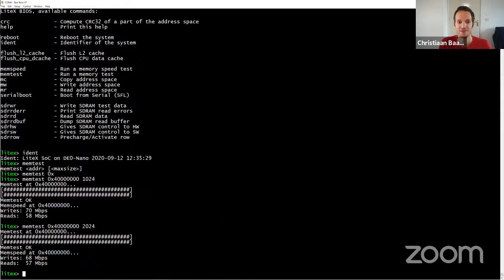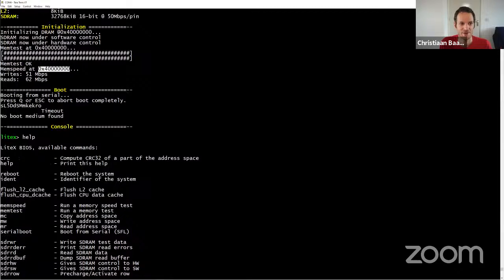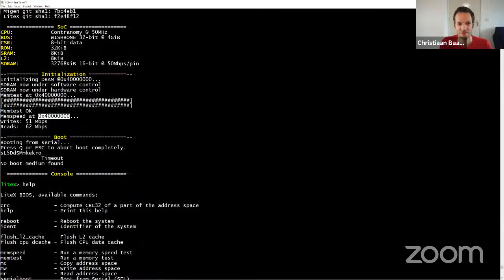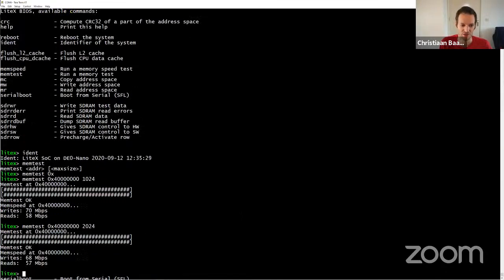We've integrated the generated Verilog inside a larger system on chip, which, as you can see here, includes SDRAM. It contains a UART, and you can build so much more inside of this system on chip builder called LiteX. So we integrated the generated Verilog into that. Then we told LiteX to build our entire system on chip, which we could run as a Verilog simulation of our entire system on chip on our PC.